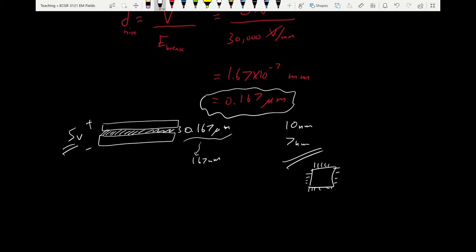That's one concern. There's another concern. Although 5 volts is the operational voltage, we need to design for higher voltages because there's a phenomenon in semiconductor materials called ESD, electrostatic discharge. This is what happens when you walk on a carpet or wear insulating shoes and walk for a while and then touch a metal door handle. You zap yourself, right? Or you shake hands with a friend and you zap him and yourself. It's the same thing. This is called electrostatic discharge. This also happens when you're handling semiconductor chips.